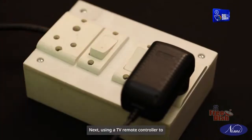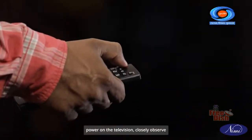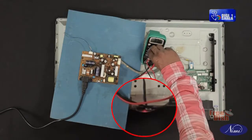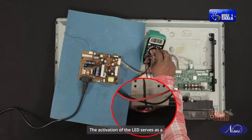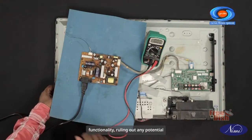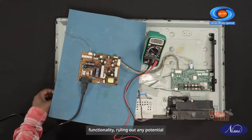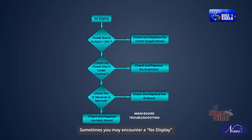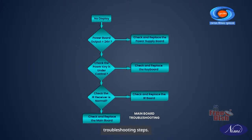Next, using a TV remote controller to power on the television, closely observe whether the LED light turns on. The activation of the LED serves as a confirmation of the main board's proper functionality, ruling out any potential power-related issues. Sometimes you may encounter a no display issue despite completing prior troubleshooting steps. In such a case, refer to the provided flowchart as a systematic guide for further diagnosis.